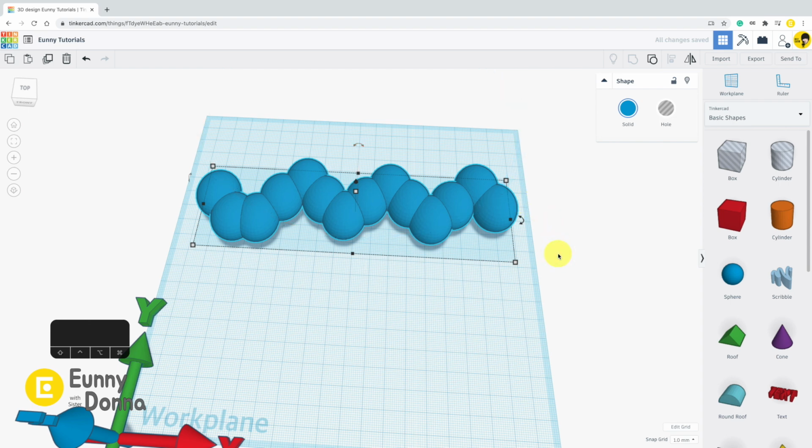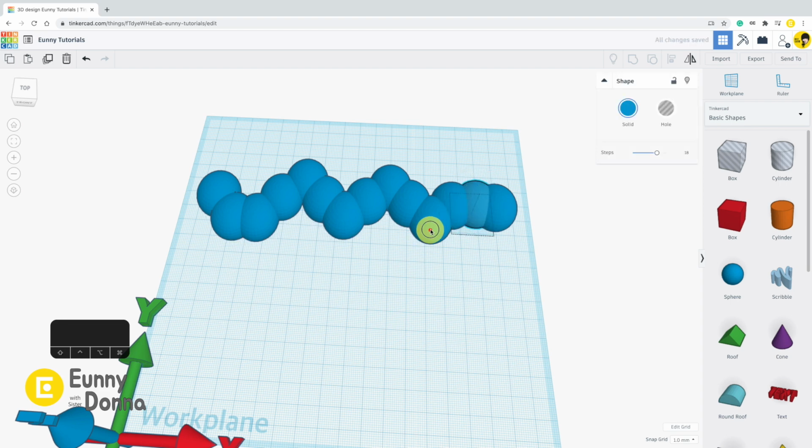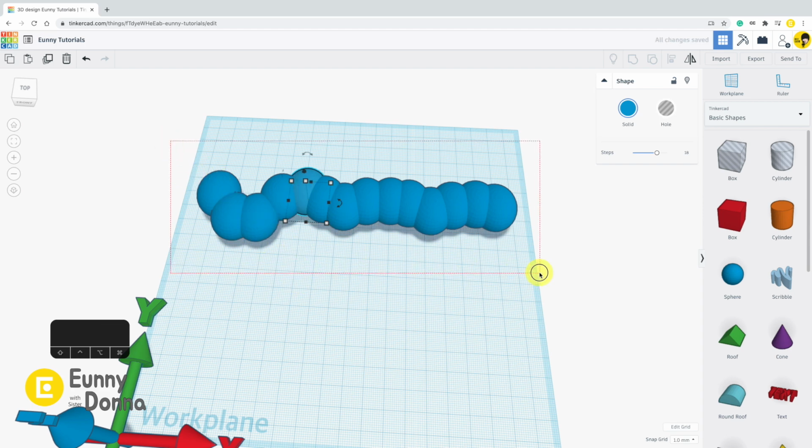If you want to release this group backwards, click Ungroup next to the Group button. The shapes will be separated into pieces. Then you can adjust each shape's size, location, and so forth. After adjustment on shapes, you can drag them again to make a group.